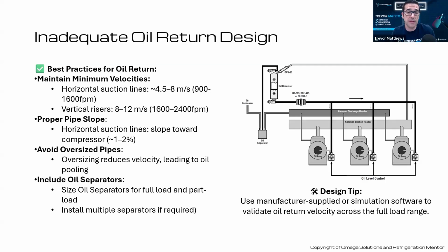in the piping design of the oil management system, which is a whole different game than designing the piping of the refrigeration system. So it's really, really important to dive into that stuff when you're doing those sizing, because I know we included the oil separator there in the sizing. So many times you need to sit down and make sure that those lines are correct. Definitely. And 99% of the time, you can rely on it and say, well, it's been designed correctly.